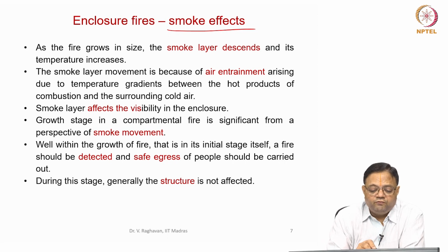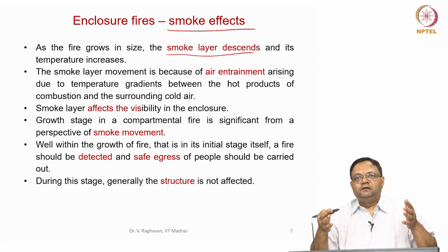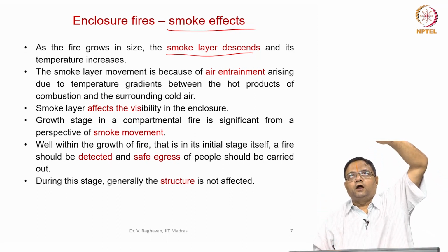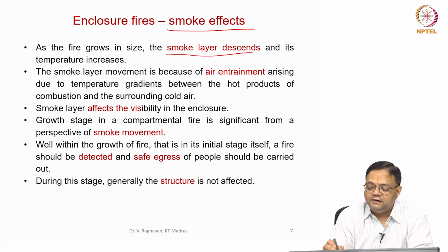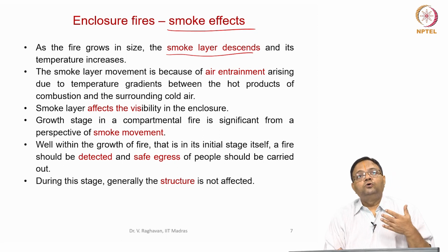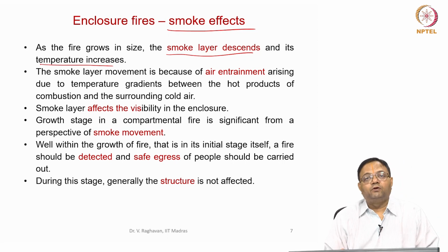So, as the fire grows in size, more and more smoke hits the ceiling, and basically the smoke layer accumulates, that is, it comes down, the smoke layer thickness will increase, the smoke layer descends, and also, since the heat release rate is increasing, the temperature of the smoke layer will also increase. The smoke layer movement is caused by the air entrainment arising due to temperature gradient, that is buoyancy forces, between the hot gases and the surrounding cold air.